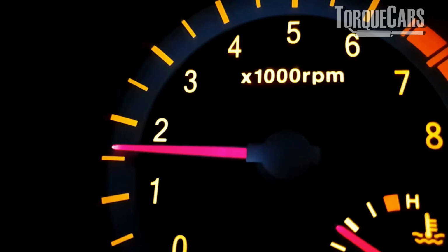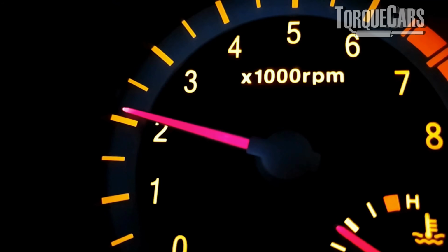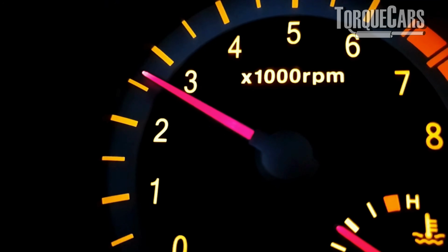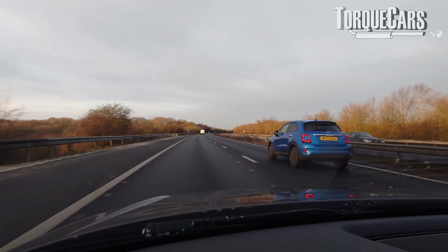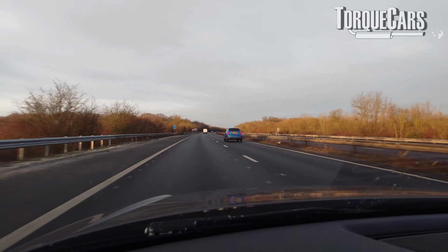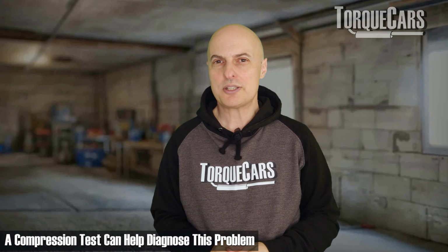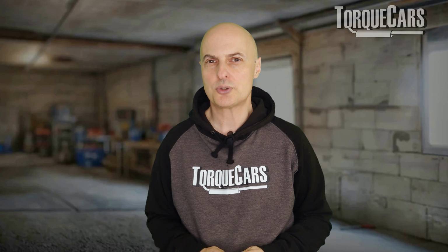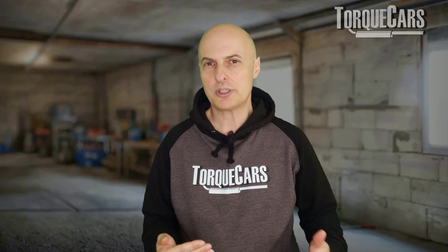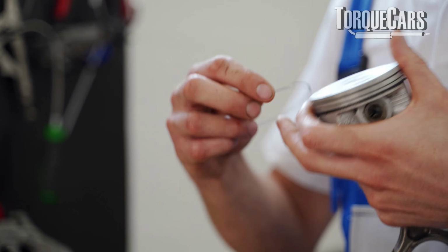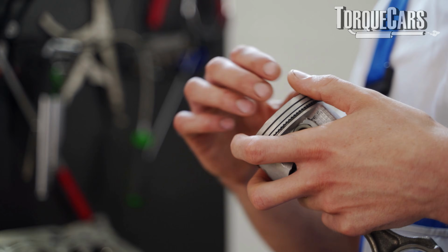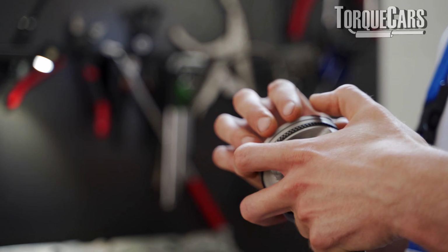Running at relatively low RPMs, it doesn't matter too much, and the engine can compensate for any anomalies there, but it will manifest itself the minute we put our foot on the accelerator. A compression test is the easiest way to determine if this is the problem. You just unplug a spark plug, put the compression tester tool in, and check the compression on each of the cylinders, and they should all be relatively close to each other. But if you have a runaway low compression cylinder, you can bet that that is at least a significant part